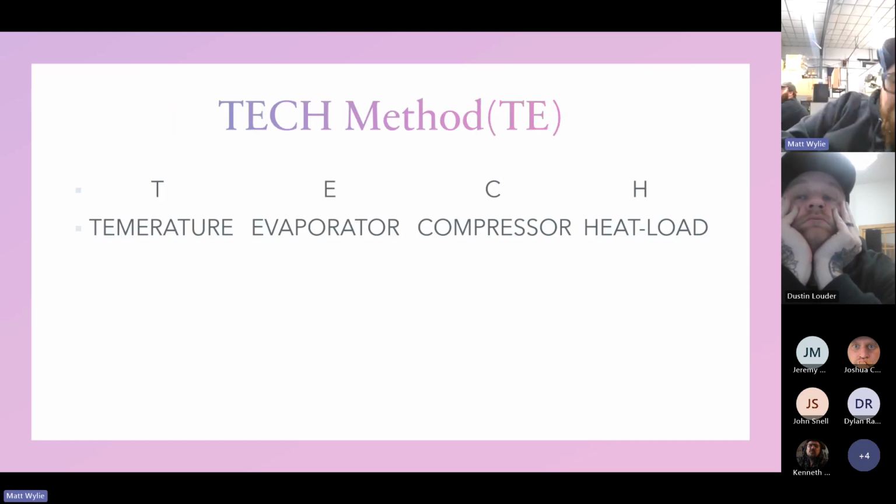And then we'll go into the TECH method. Basically TECH stands for temperature, evaporator, compressor, and then heat load. I've sent Dustin before a little tech sheet, and on a service call, you follow the steps, and it can basically walk you through the service call.